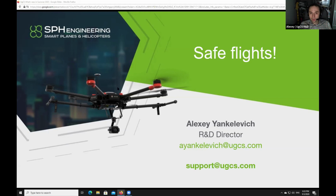A question about the M600 Pro: if I lose the RC connection forever, will it return back to home when the battery reaches critical power if we choose continue for safe mode? Actually, you have different safety options for battery and for RC, so you can configure them separately. On RC loss, you can have a separate failsafe. So I think that can solve your issue.